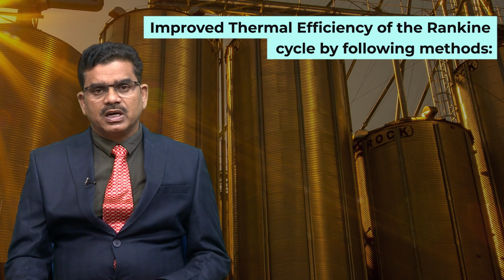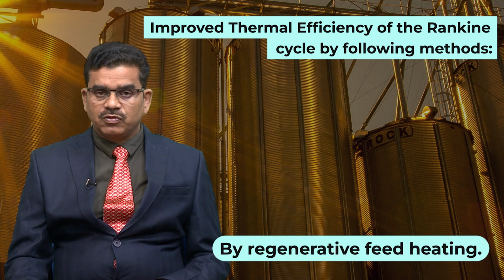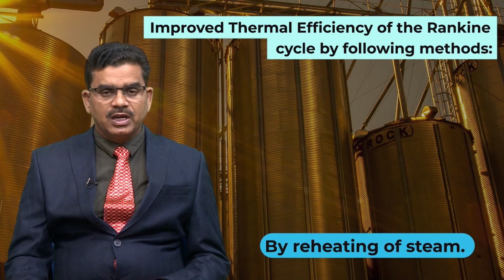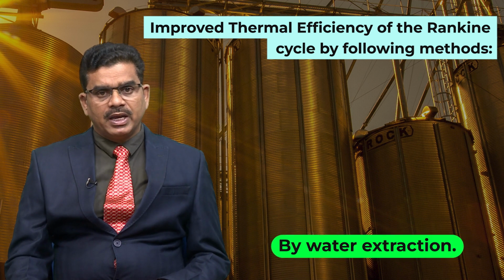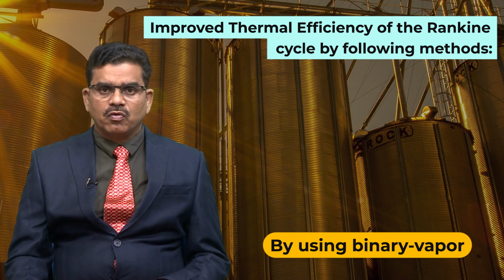We can improve the efficiency by regenerative feed heating, by reheating of steam, by water extraction, and by using binary vapor. Using these accessories we can improve the efficiency of the Rankine cycle.